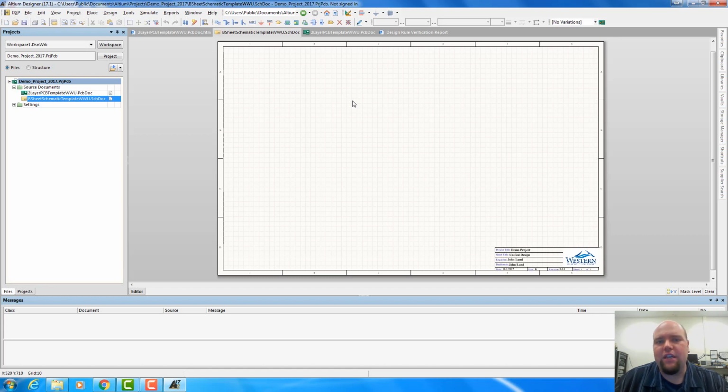And that could be you connect pins to that header connection. Could be you directly solder to it. A 0.1 inch spaced header is a fairly good sort of universal way to make a signal connection to a board. It leaves you with a lot of options.